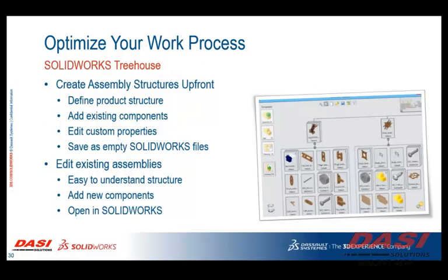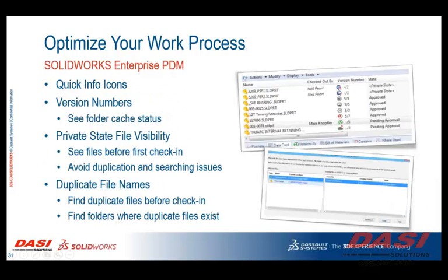Well, in SolidWorks 2015, we've added some tremendous new capabilities, and I'm going to go ahead and show these here in just a second. But I want to talk about each of these. SolidWorks Treehouse is a way for us to predefine assembly structures or interrogate an existing assembly, frankly. There's some great functionality in both of those. There's new quick info icons, columns that are going to show up inside of your Windows Explorer Vault view, not just in your SolidWorks tab. It gives you details and feedback about the status of the file, whether it's the latest version, older, newer, or frankly, whether it's not cached locally, which is a great new function based on this version column.